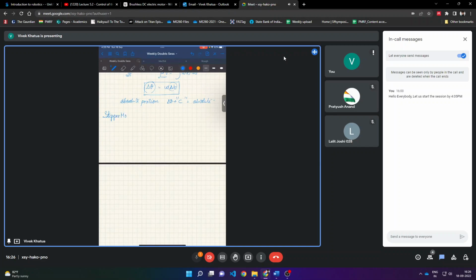And in a stepper motor, the construction is that it works on the principle of stepping. How do I do this? I have a stator that has some coil wound on it, right? And this is arranged with really fine spacing between them.